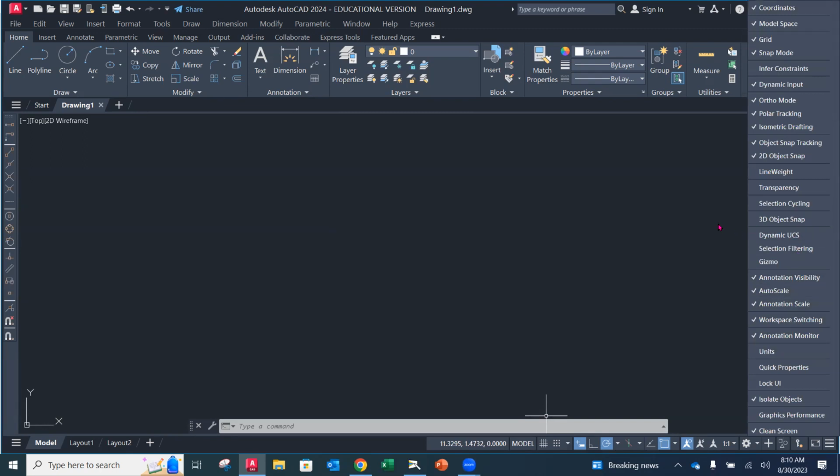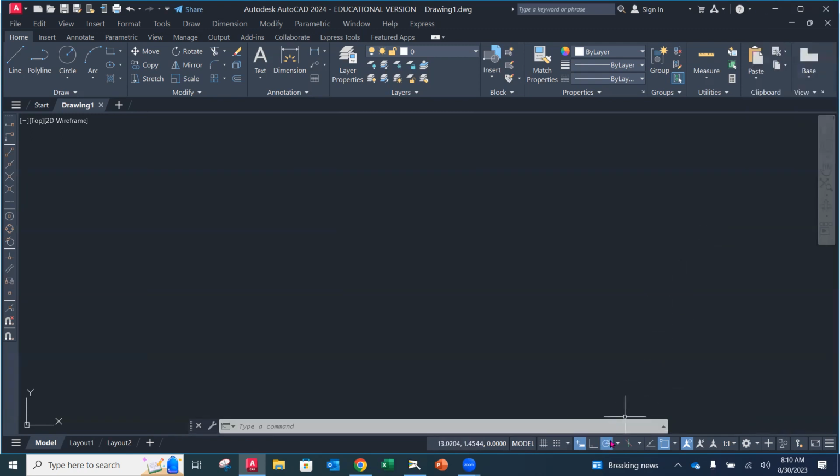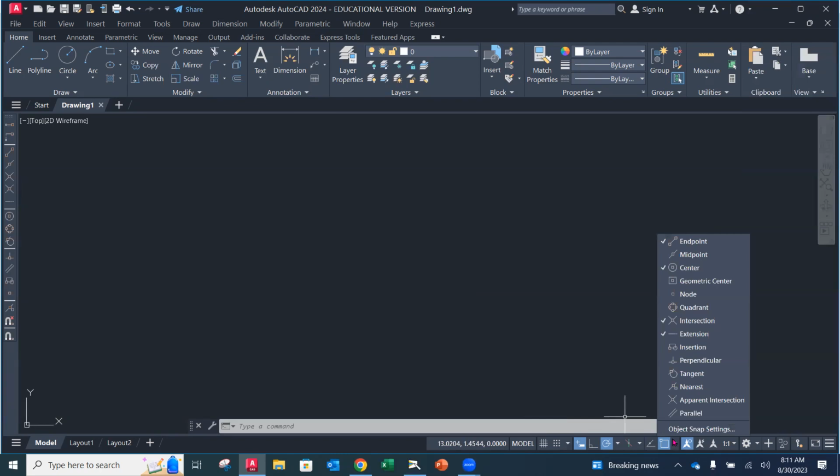Okay. So I'm going to click on the outside here. Also make sure that your object snaps, running object snaps, are here. And then as we look at that arrow down, I'm going to click on that. Running object snaps, anything that I have clicked here is always active. So you have a list of them. The ones that I tend to gravitate to have available all the time that automatically come up are going to be endpoint, center, intersection, and extension. Okay, those are my favorites, if you would. Actually, I don't like extension. I like tangent.